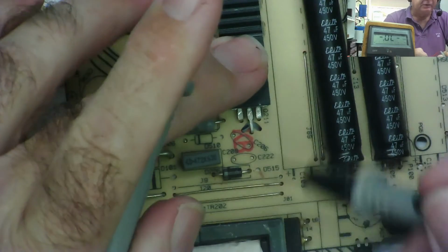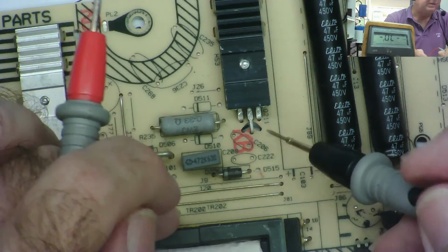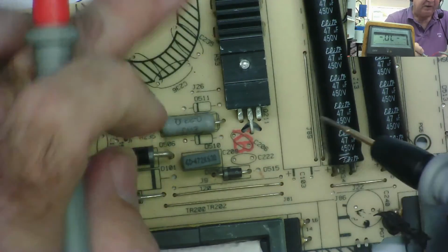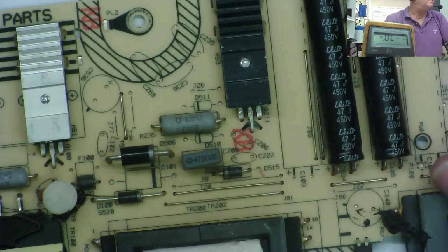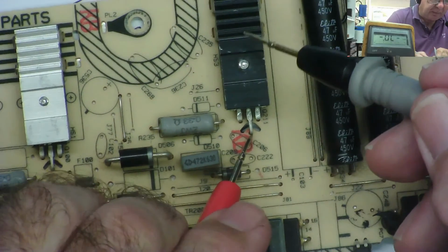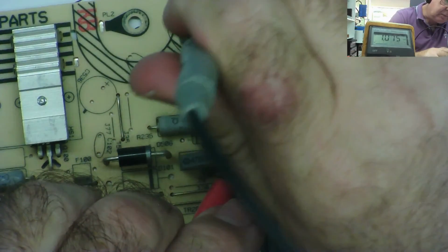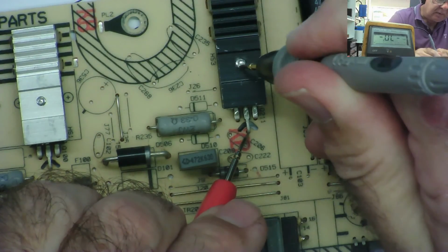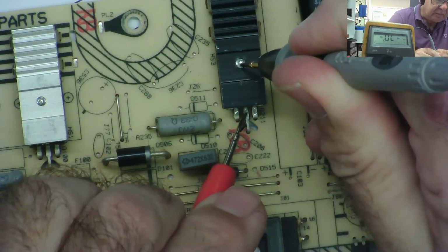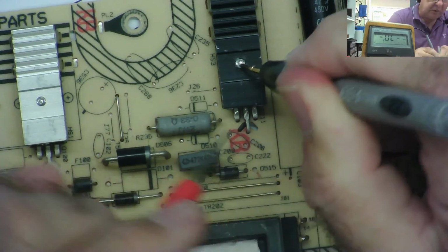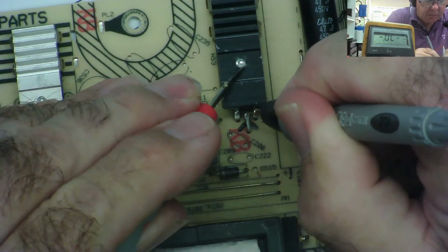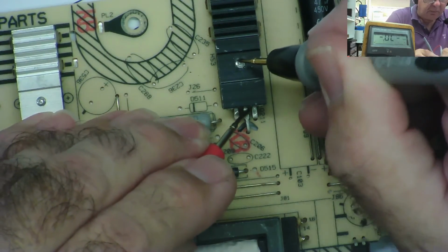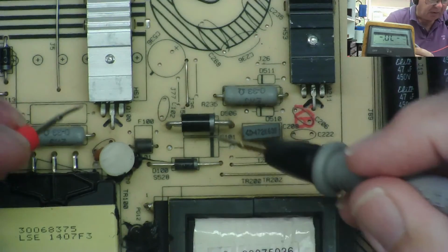Watch out, these heatsinks are connected to the collector. If there's a high voltage on that collector, and the fact there's a cutout in the circuit board here tells me there is a high voltage on that collector, there's a high voltage on the heatsink, because it isn't insulated from it. Actually, no, it is insulated. No, I thought I had a connection there. That's strange, isn't it? No, I don't have a connection to that. I thought I did. Watch out for that. Sometimes heatsinks can be live.